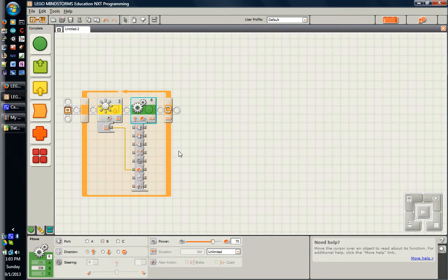One, we can make anything that the light sensor reads that's greater than 50 just top off at 50% power. So if it reads 75, that gives 50% power. If it reads 100, that gives 50% power. The other option would be to use a gradient that just halves the light sensor reading. So if the light sensor reads 100, the motor spins at 50% power. If the sensor reads 40, the motor spins at 20% power, etc.